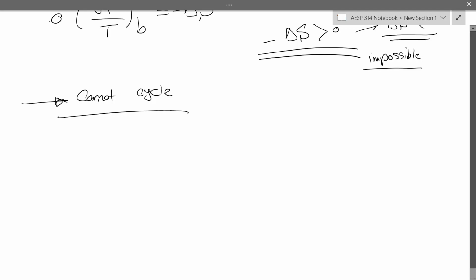and like the Carnot cycle, let me see. The efficiency of a Carnot cycle is usually 1 minus Tc divided by Th. It is not on my notes, for whatever reason I don't have this efficiency on my notes, but make sure you write this down. So efficiency of a Carnot cycle, 1 minus Tc over Th. So that's the maximum efficiency we can achieve.